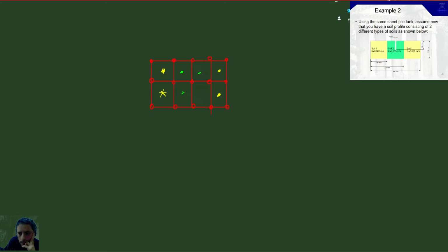If water has to go, it suffers a head loss because of the hydraulic conductivity or resistivity, which is the inverse of conductivity. So water that goes from this node to here loses head because of the resistivity of the soil that's there, right? So that means it's the material in between that matters, not whatever I find at the nodes.